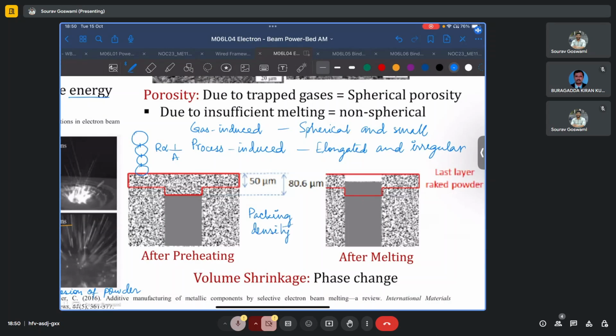This is also something we discussed when talking about the roller-based recoating mechanism, where we said that a roller has 2 degrees of freedom, one related to its translation, the other related to its rotation about its own axis. Now, if we have a forward rotating roller, that is, the sense of rotation is also along the direction of its translation, the powder bed tends to be better packed and the packing density tends to be higher.